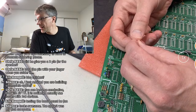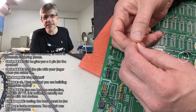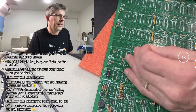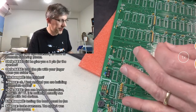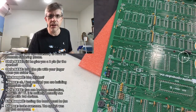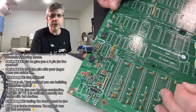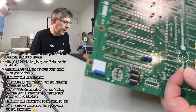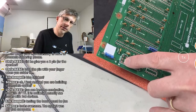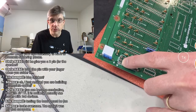So yeah, Eric, he says testing the board must be fun. I think this is kind of what maybe it was Chris said last time, that since this is like TTL components and they're huge, there's actually, knock on wood, not a lot that can go horribly wrong unless you're like me and soldering your transistors backwards. What I actually did take the multimeter, and last night I took, so here's where the power connector goes, and I just used the continuity tester to make sure that nothing, at least at this point, was shorted out.